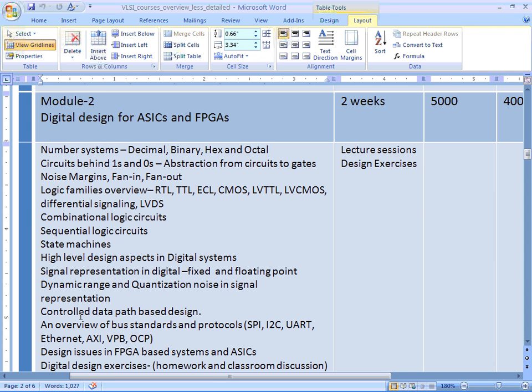For example, if you look at NXP, which is the Philips silicon division, one IP is coming from ARM, which is the ARM core, another IP is coming from, let's say, USB 3.0 from another company, Ethernet IP is coming from some other, and some multimedia IP is coming from Broadcom, let's say. Now all this put together, you are taping out one chip. Then this is actually a system on chip. So industry sees it that way.